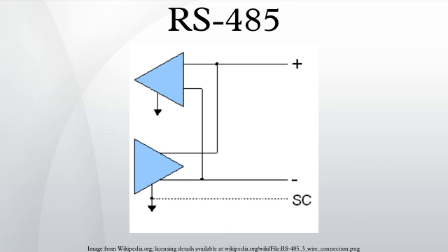Termination resistors also reduce electrical noise sensitivity due to the lower impedance, and bias resistors are required. The value of each termination resistor should be equal to the cable characteristic impedance. Star and ring topologies are not recommended because of signal reflections or excessively low or high termination impedance.